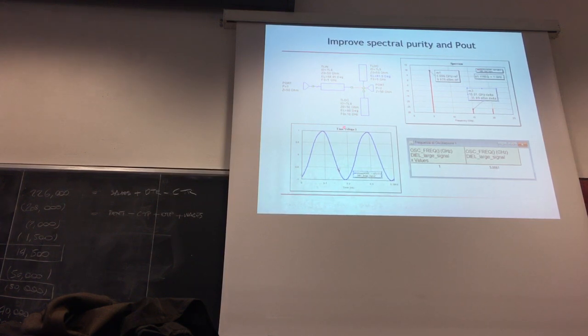As we have seen last time when we discussed this solution, in this way, a voltage different from zero may happen only at the fundamental frequency, because at the harmonics, this is the second, this is the third harmonic, the voltage cannot be different from zero, because here we have reported that this frequency is a short circuit.